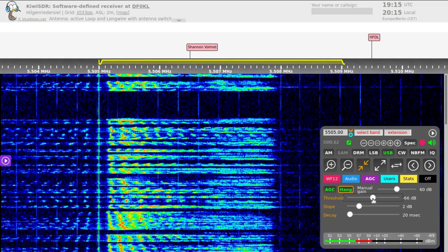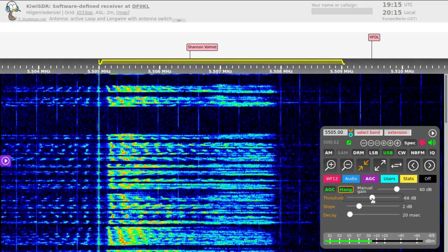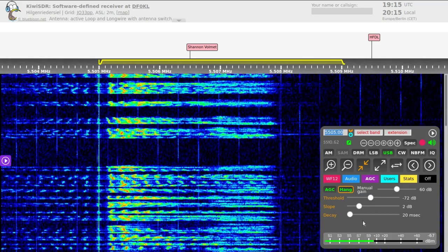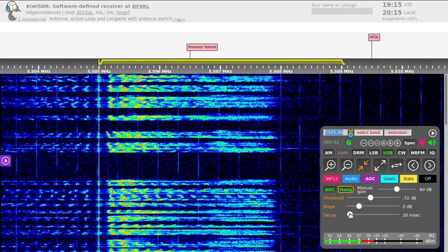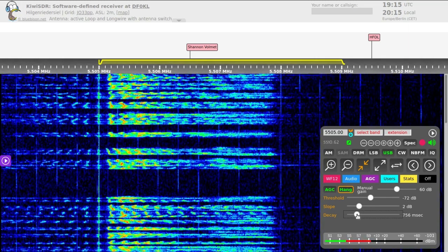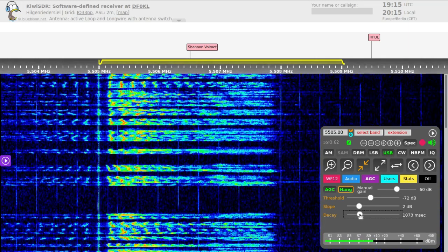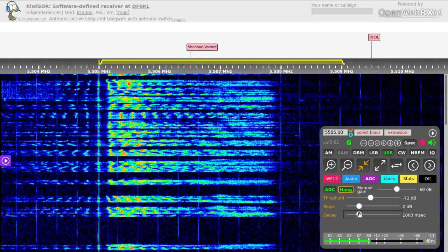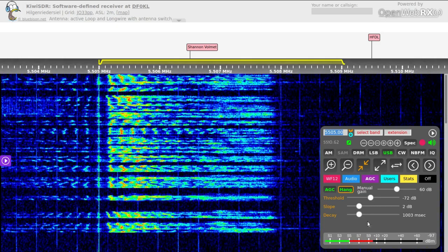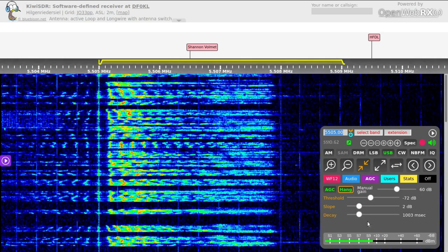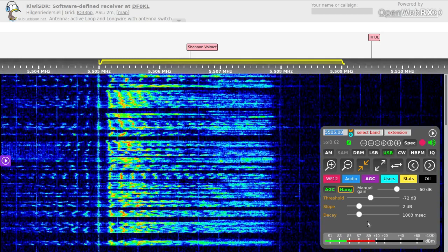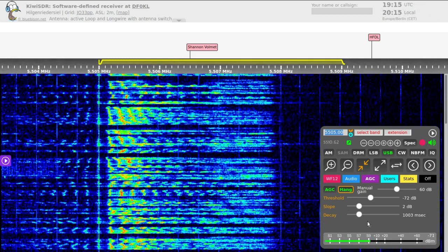You can see here a setting someplace around, let's say, minus 72, keeps the gain reduced. And then protection against strong fades. You can then set a decay time either near the default 1000 or set it to a longer time to protect in between brief pauses.